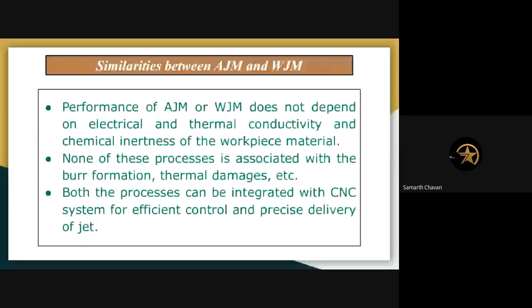The fifth one is that none of these processes, that means AJM and water jet machining, is associated with burr formation. Okay, none of these processes is associated with burr formation or thermal damages. Okay, and the last similarity is that both the processes can be integrated with the CNC system for efficient control and precise delivery of the jet. Okay, so you can go for automation.